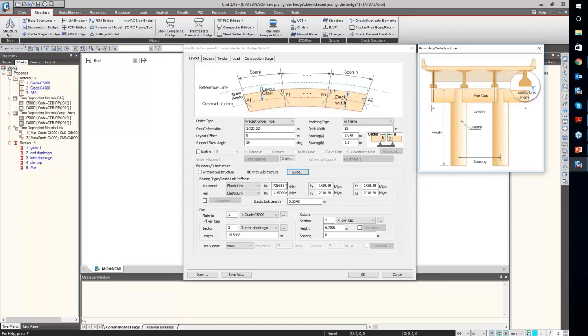Kx is the local x direction of the spring. When I assign that, it is going to come in the global z direction. In that direction, the stiffness is going to be very high, so I have just assigned 1e8 stiffness. In the other two directions, I am giving it 1000 stiffness.